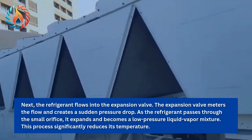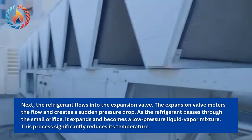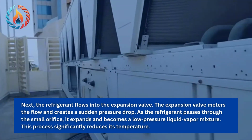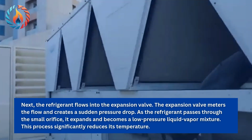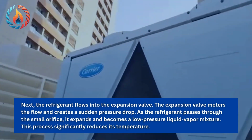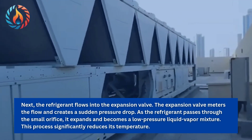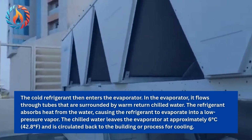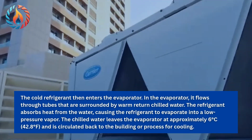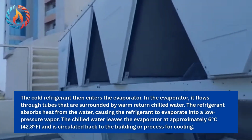Next, the refrigerant flows into the expansion valve. The expansion valve meters the flow and creates a sudden pressure drop. As the refrigerant passes through the small orifice, it expands and becomes a low-pressure liquid-vapor mixture. This process significantly reduces its temperature. The cold refrigerant then enters the evaporator. In the evaporator, it flows through tubes that are surrounded by warm return chilled water.